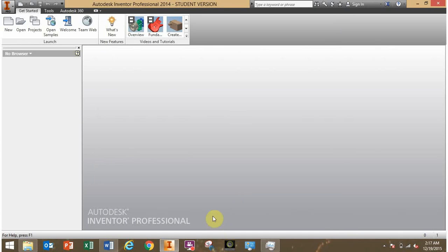So cancel that. You've finished exercise 1. I hope you can apply the tools that we learned here in exercise 1 to your project and to practice documenting other assemblies as well. Remember, when you're documenting assemblies, make as many drawings as you need. Also make drawings for different sub-assemblies rather than trying to document every part on the same drawing. Remember: sub-assemblies, section views, exploded views, parts list. Hopefully this will help you clearly define what your assembly looks like.